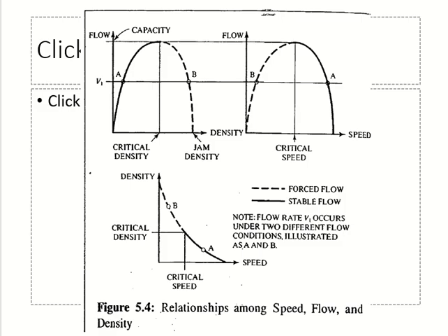So we have speed and density. We already discussed it in the last lecture. Density is how many vehicles you have in 1 mile, right? If I have more vehicles within a fixed space, what will happen to density? What will happen to speed? Decrease. It will decrease, right? So density increases, speed decreases. Clear?